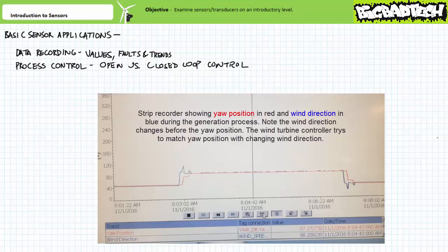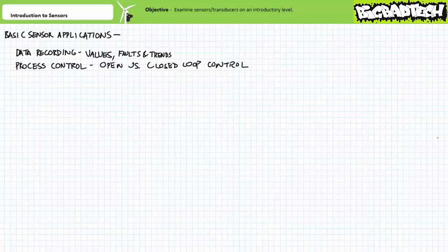Additionally, historic trends can be captured and analyzed using the accumulated data. For example, if the vibration sensor on the main shaft bearing indicates an increasing trend, a technician can be dispatched to perform inspection or preventative maintenance before the issue becomes a deal breaker. This type of predictive maintenance would not be possible without a sensor that not only detects a quantity, but also measures and quantifies it.